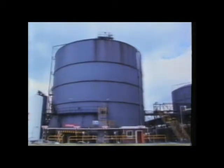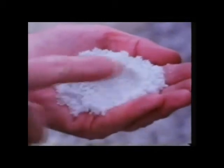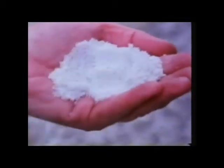To keep the liquids inside as cool as possible, this is how the storage tanks are constructed. The big tank inside the outer casing holds the liquid oxygen or nitrogen. It's supported on a heat-insulating base. The space between the inner tank and the outer skin is packed with little pellets of porous insulating material, rather like cavity insulation in the walls of a modern house. This is the insulating material made of glass.